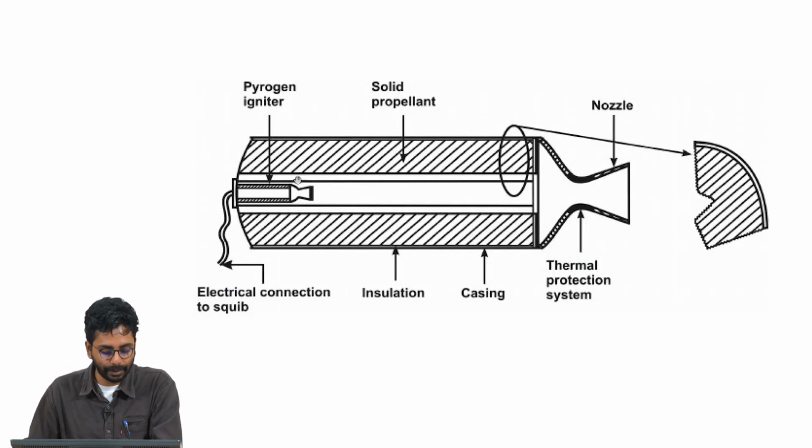So, we have a burning solid propellant issuing hot gases into the chamber, into the port as it is called, and this will cause the hot gases to flow through the nozzle. The nozzle, because of its dimensions and the thermodynamic state of the gases that are coming out, can accept only a certain maximum flow, under which condition the nozzle becomes choked.